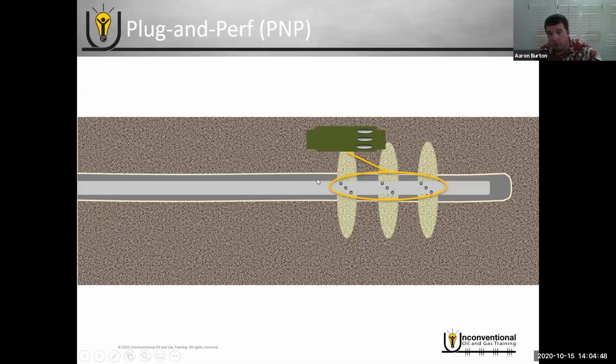So what they'll do is they'll put sugar water in it so that the cement won't harden, and then it's still in a liquid form. Once you're ready to begin fracturing, you can push through that wet cement and into the target reservoir and begin your first stage frac job like that.